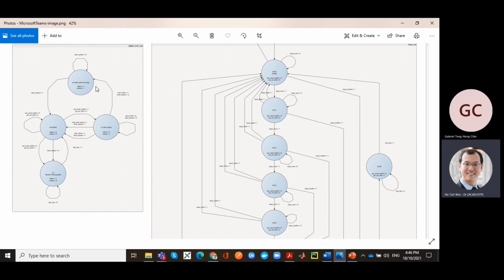Because again here, the inputs here can also be an input state here, you see. But as long as you ensure that whatever is coming from here is always well defined, and whatever is going from here is always well defined, you should have no problem. You can have cross-coupling state machines. So you go ahead and try it out. Just encode all these in Verilog and simulate it, and you will see very nicely that it will function. If it doesn't, just WhatsApp me and then we'll have a look at it.